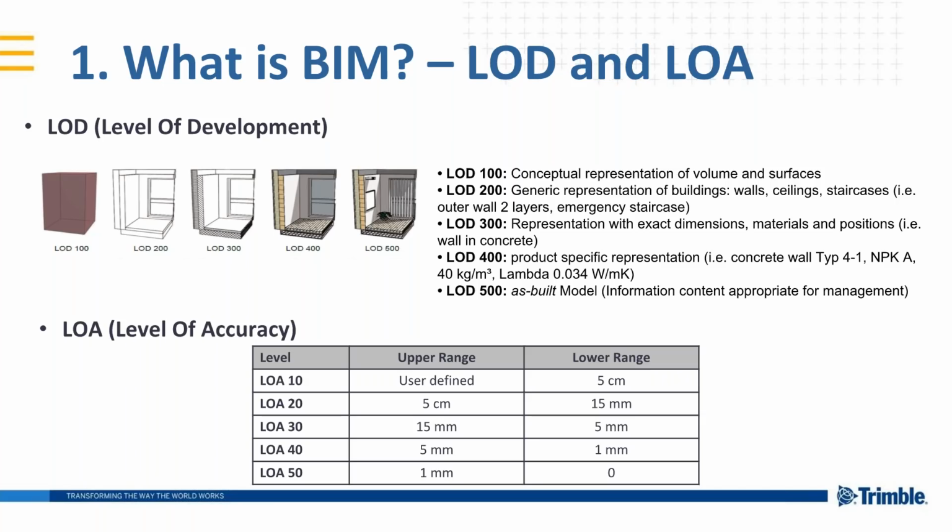Yeah, so it's country-wise mainly. So each country is developing special standards for BIM and BIM implementation and different levels, level 1, level 2. But it is mainly, as I say, country-based. But you could also find a variation inside a country. For example, imagine that we have in Germany these 5 levels. And you get in the project requirements, we want LOD 300, but additionally we want the U value, an energetic value of each window, because it's needed for the energy calculations of the whole building. So, mainly the question is decided country by country.